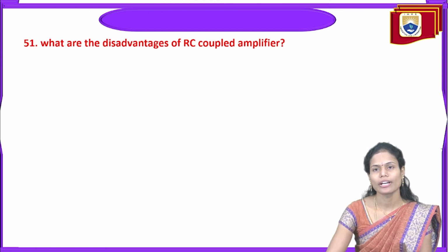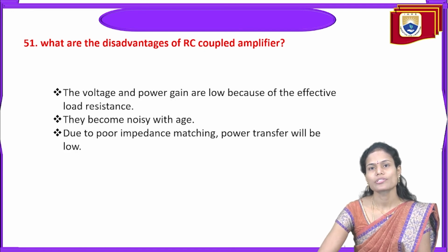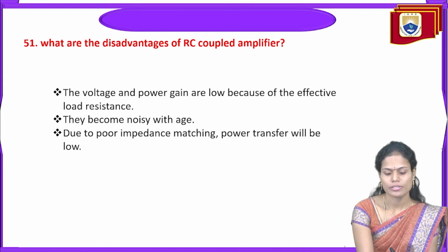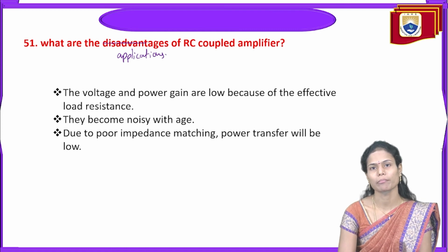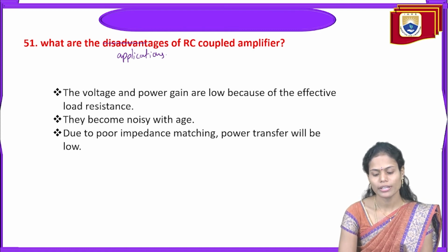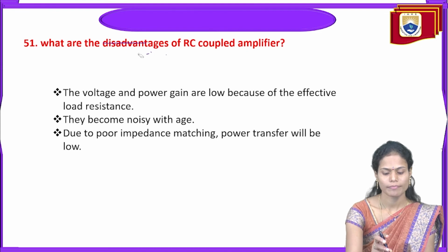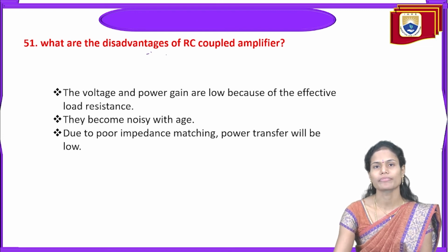And next, what are the disadvantages of RC coupled amplifier? Here the voltage and power gain are low because of the effective load resistance. They become noisy with age. And due to poor impedance matching, power transfer will be low in the case of RC coupled amplifiers.